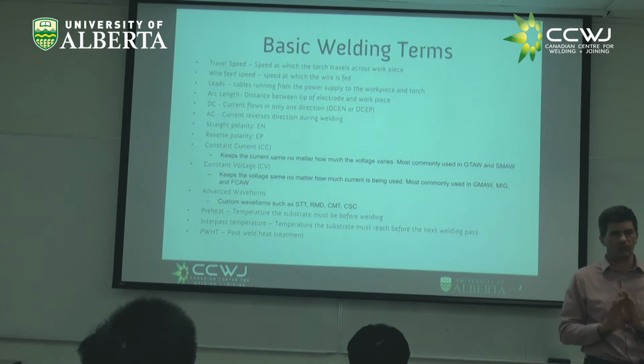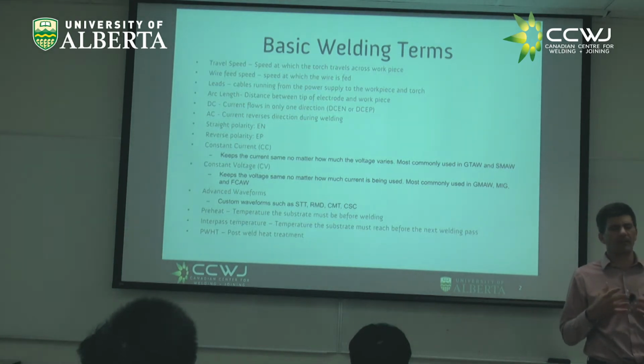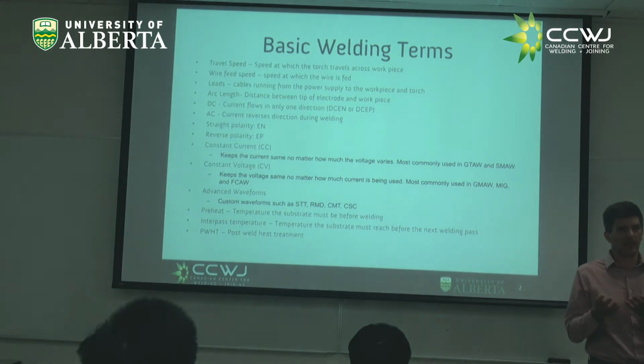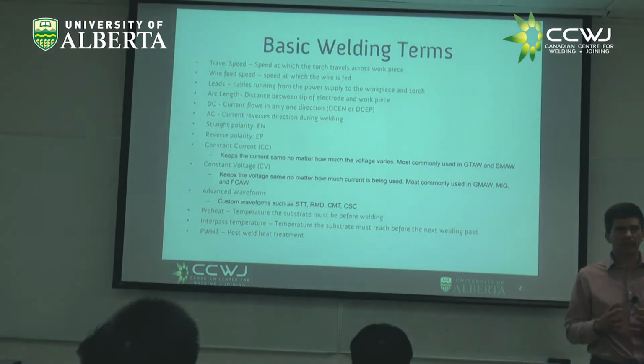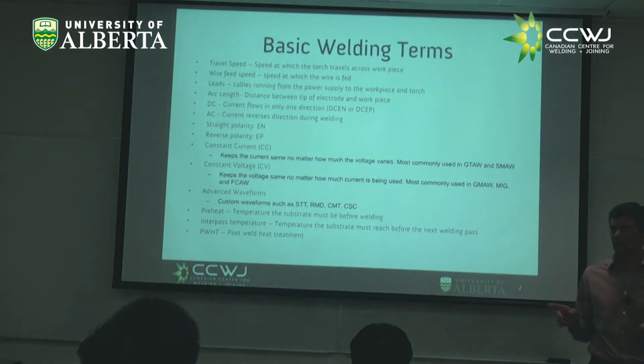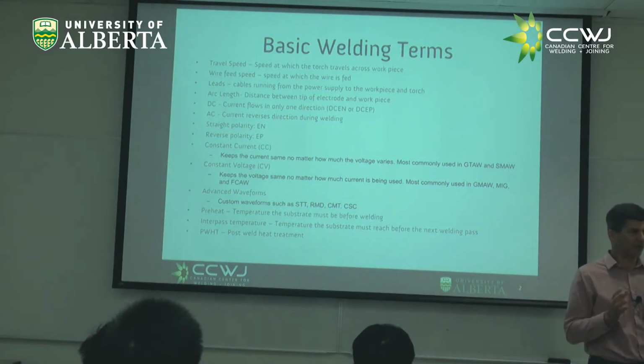I have a question for you. I haven't taught you anything, but intuitively, if I have a higher preheat, I'm welding on something in which I increase the preheat, do you think the weld is going to cool faster or slower? Slower, right? So I didn't teach you, but you know something that is super important. How many of you are material scientists here? Okay, so if I cool down slower, and I'm working on steel, what do you expect the steel will be, harder or softer? Softer, right? So you already know something extremely important about welding.